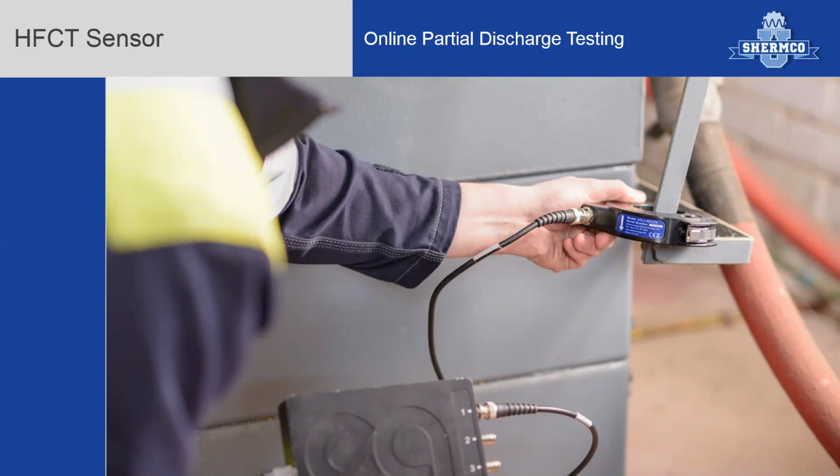High frequency current transformers are a reliable method to measure these high frequency PD pulses. These pulses spread out onto the ground grid like ripples in water. They are especially useful for quickly testing for internal PD in a large area, such as if PD is present in a power transformer, or if PD is present in a long section of cable, or even if PD is detected or possibly sensed in an entire substation. The high-frequency CT sensor has a split core, and so it's simply clamped around the low-resistance grounding lead.